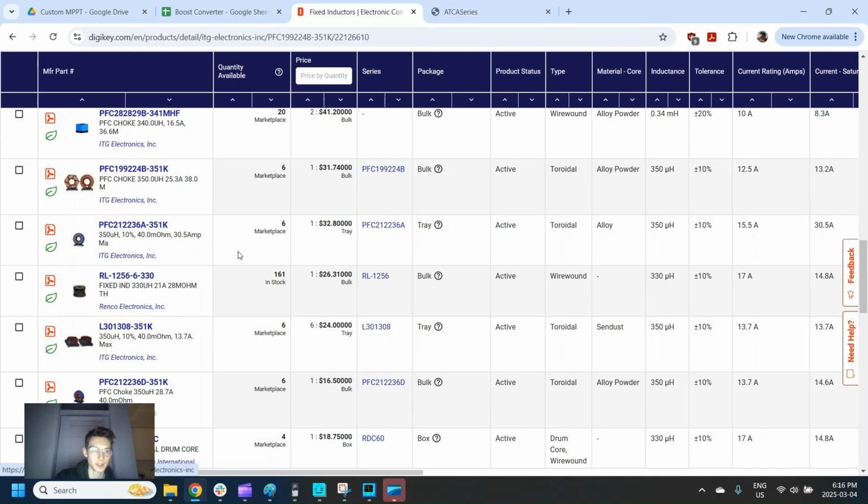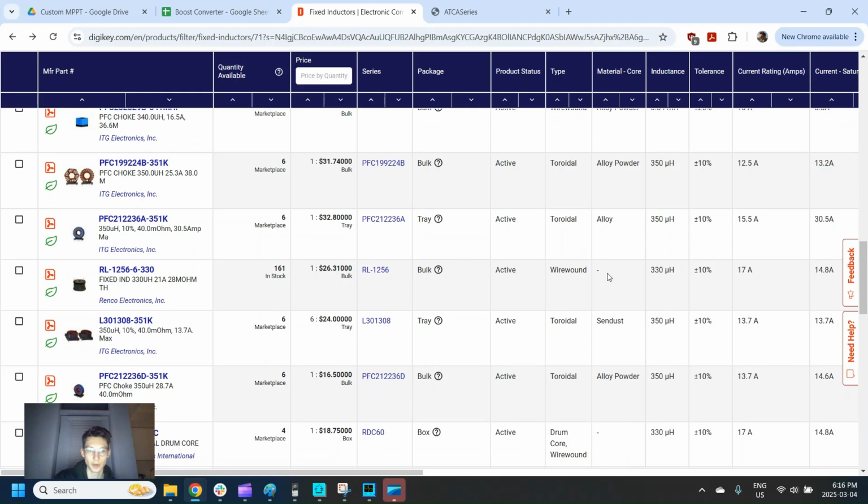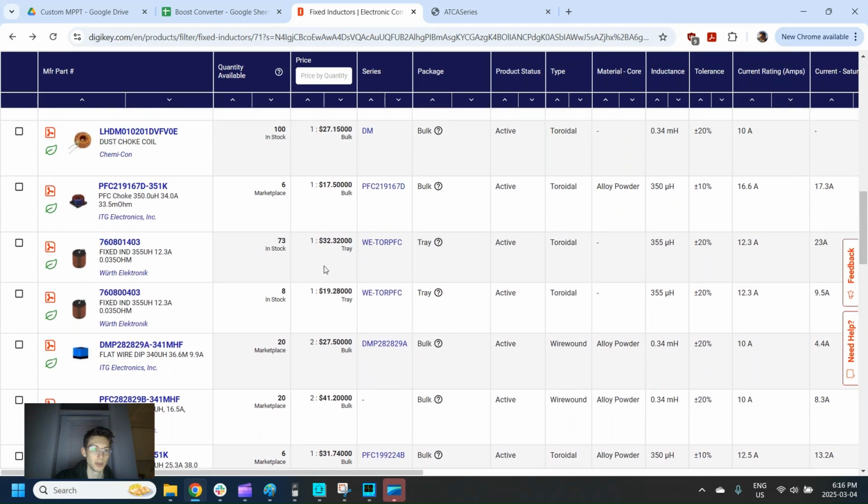One thing to note is that a lot of times people in power electronics don't like to buy their inductors. They prefer to actually just build their inductors. So you'll buy a core, and you'll buy some metallic wire, and you'll wrap it around and you'll put it on some base. This might be a good option too. I think if you're just building something right off the bat, don't go for that. But if you're wanting to do the hyper efficient, get something very precise, then definitely worth building something yourself.